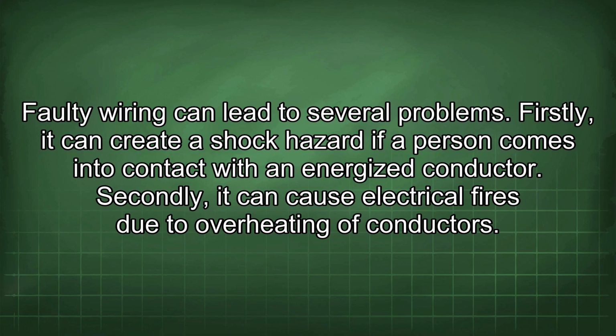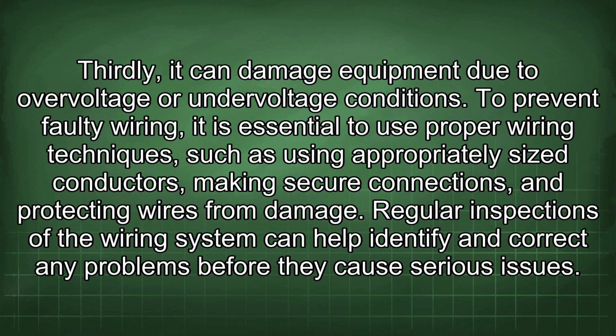Faulty wiring can lead to several problems. Firstly, it can create a shock hazard if a person comes into contact with an energized conductor. Secondly, it can cause electrical fires due to overheating of conductors. Thirdly, it can damage equipment due to overvoltage or undervoltage conditions.